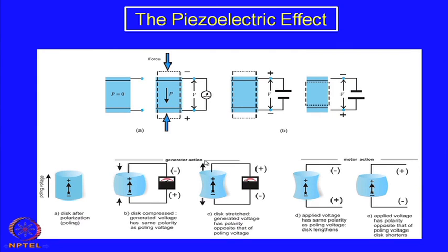If you reverse it, if you now put in tension, then a reverse voltage will generate. So, this becomes positive and this becomes negative. Now, in addition to that, one has to also notice when you compress it, it is not only changing its dimension along this axis, but it is also changing its dimension in the orthogonal direction, or the right angle to that, and that is basically because of the Poisson's effect, because of the mechanical deformation.